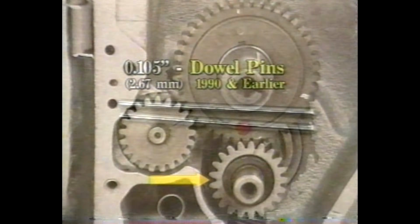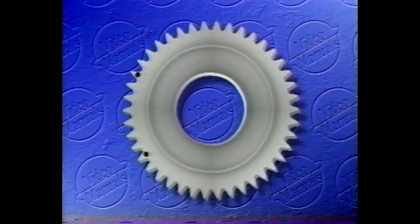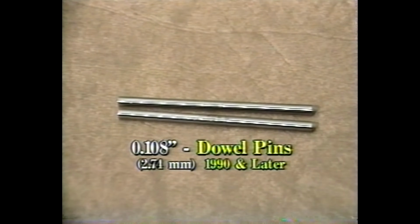For this, we must use a set of dowel pins that are 105,000ths of an inch in diameter, which is for camshafts 1990 and earlier, and this is designated by a single groove or no groove around the front face of the cam drive gear. For camshafts 1990 and later, which are designated by 2 grooves on our cam drive gear, we would use dowel pins that are 108 thousandths of an inch in diameter.